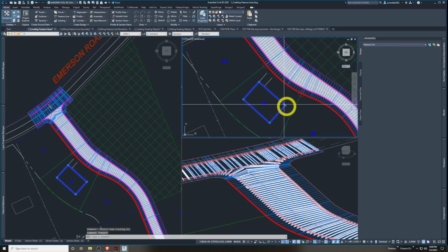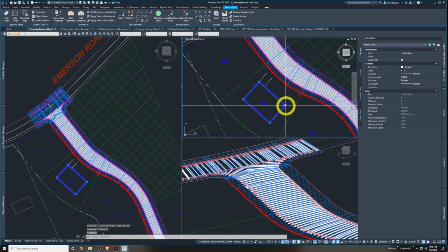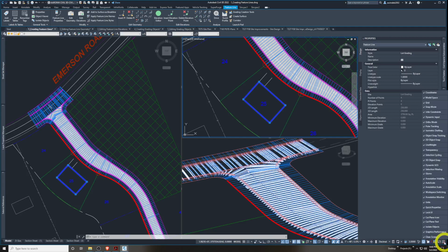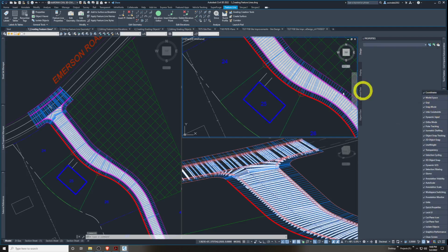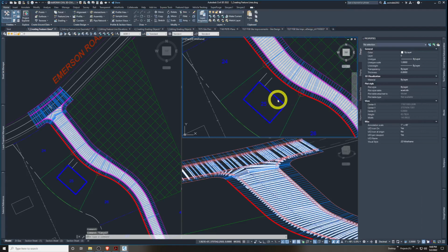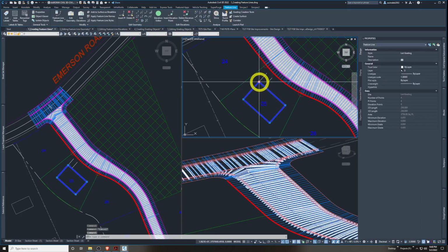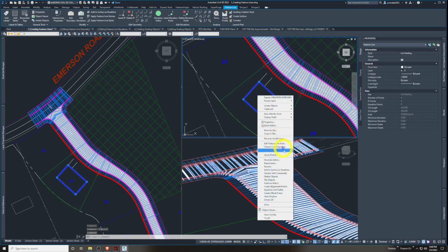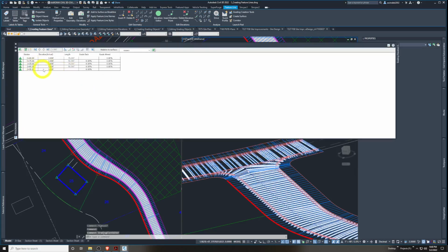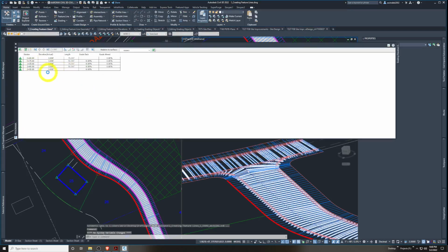So I go click that, the new feature line, I have 0 down there. So that's one quick way. A lot of times I'll move around. See, it's moving in the XY down here. My coordinates, if you don't have that open, go to the hamburger box, pull down and turn it on here, coordinates. I use this all the time for just quick spot checks. And pick on that, look at that. You can also right click and go to elevation editor and you notice everything's on 0. So we don't have that going on yet, but that's good enough for now.